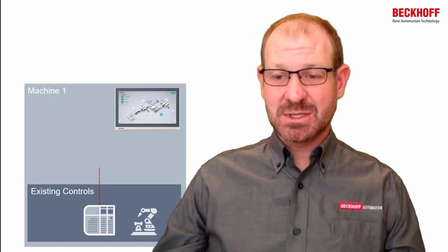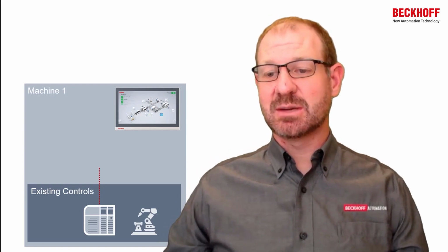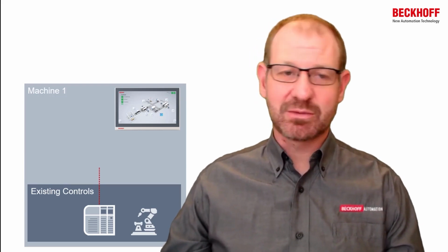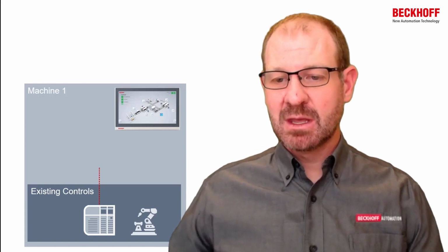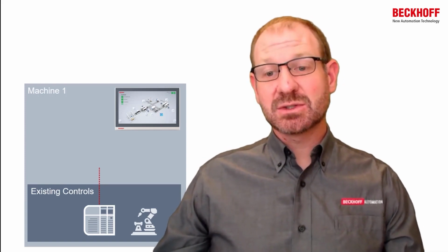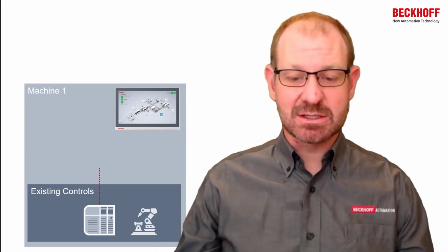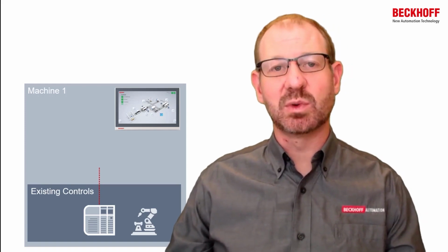As Sven mentioned, OPC makes a perfect vendor-agnostic communication channel between devices and software services, eliminating the need to manage multiple different proprietary protocols from every single hardware controls vendor. Many modern industrial devices come enabled with OPC. Sometimes it's just enabling it in software, but the device is capable of having OPC directly on board.